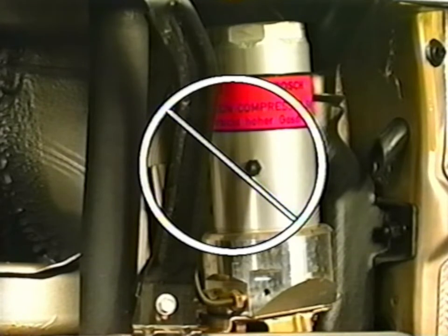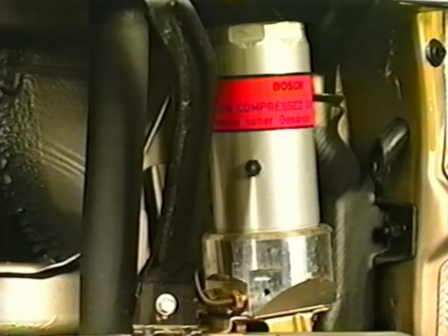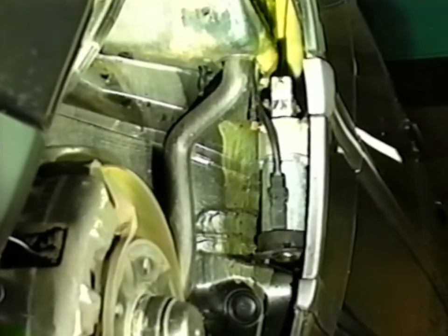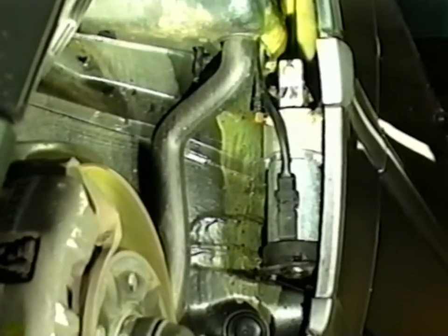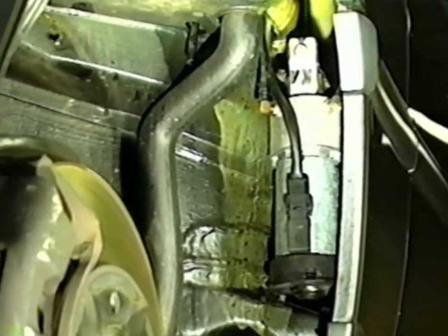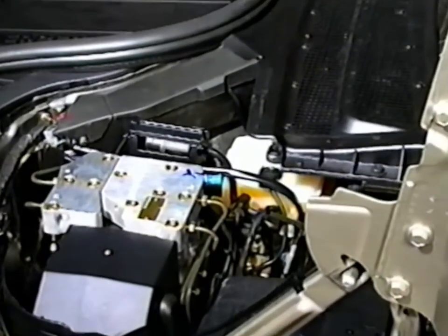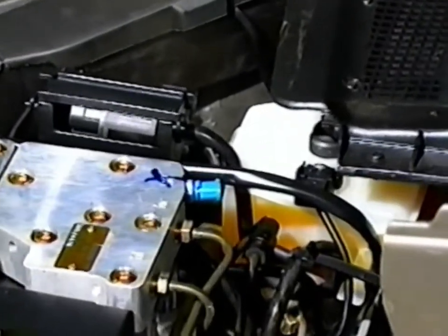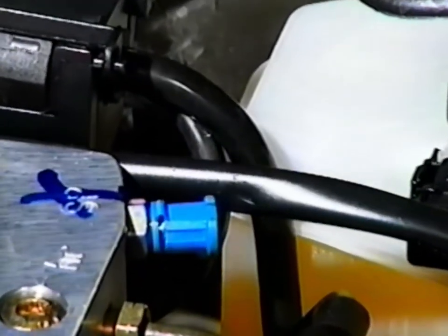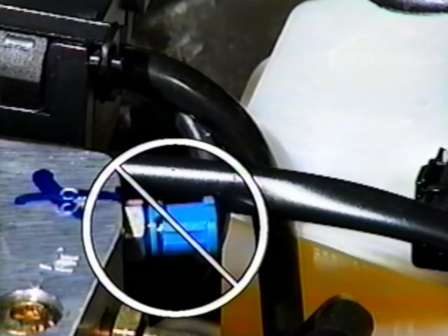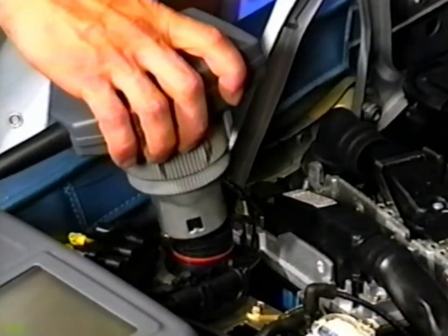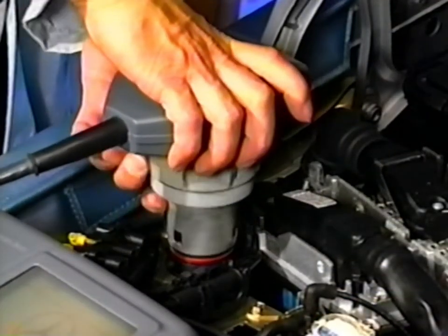Eliminating the pressure reservoir was made possible by installing a larger charging pump with increased performance, making it unnecessary to store pressure. An important repair point related to ASR4 is the elimination of the bleed screw, since the ASR4 hydraulic unit has a self-contained, closed bleeding system. The bleeding procedure is accomplished electronically using the handheld tester. The procedure is found in the diagnostic manual.